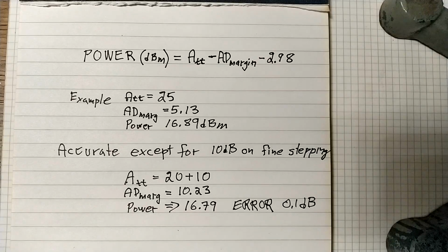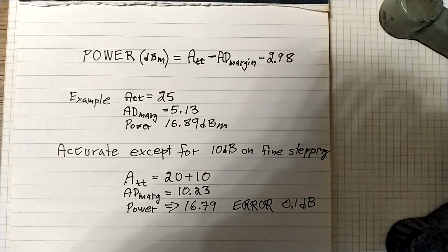Not much to worry about, but the other settings are better, and the 10 dB setting is never needed because it's better to step up on the coarse scale. Unless, of course, I would need the full attenuation of 30 decibels. But that's quite high power that I'm not likely to get from oscillators.